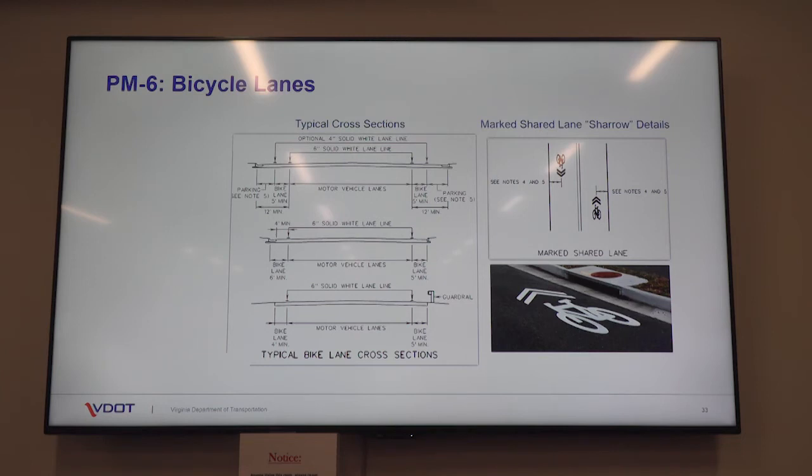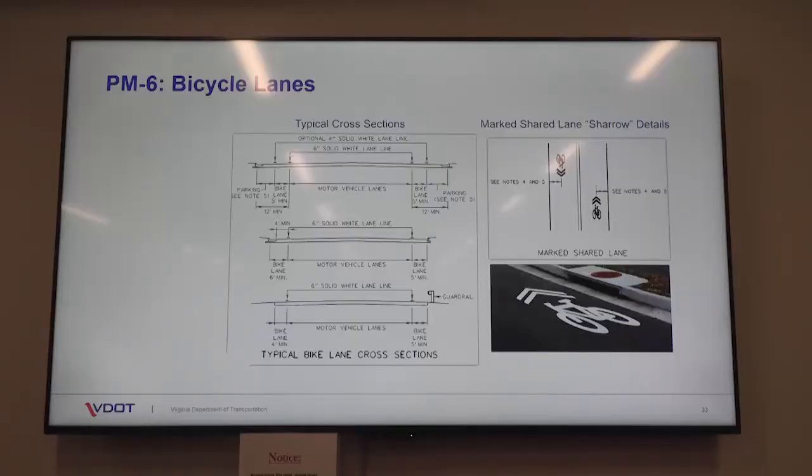Question: Isn't that supposed to be in the middle of the lane? The Shero? Yes. Well, it actually depends. If you have a mixing zone, then sometimes they're staggered across as you bring your cyclists back from a protected bike lane over into mixed-use traffic. It should be placed where the bicyclist would normally be riding, so that the driver's aware that's the case. I said should is the operative word. If I can add to that, our standards do state the placement for the Shero, and it does match the recent guidance that's out there from bicycle planning advocates about where to laterally place it. I think your question may come from that photo right there, where visually it looks like that may be closer to the curb than what our standards would actually require, although I can't really tell for sure.